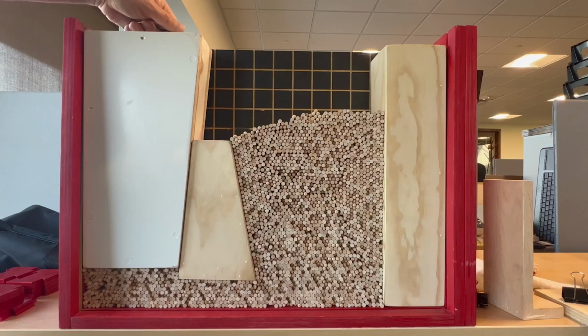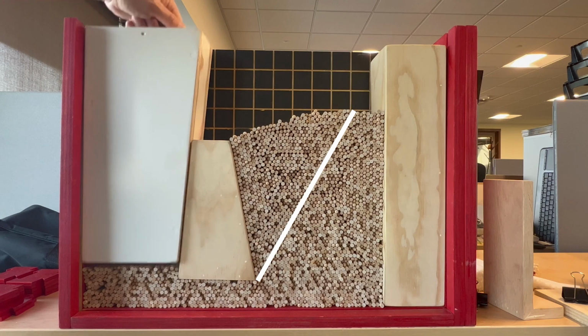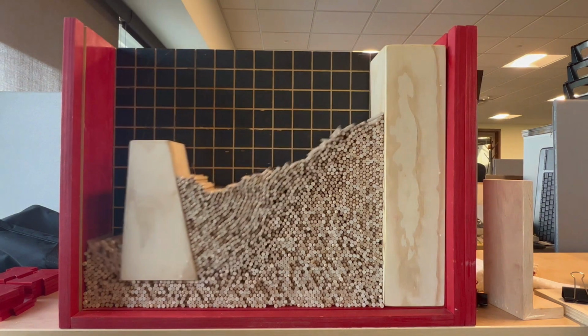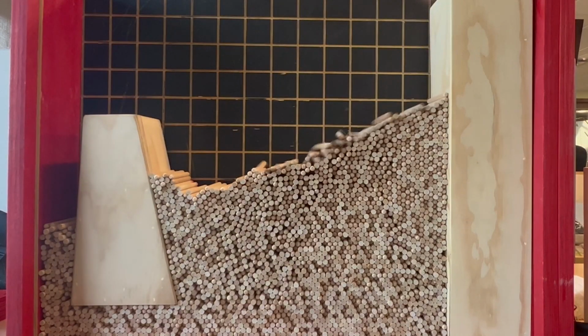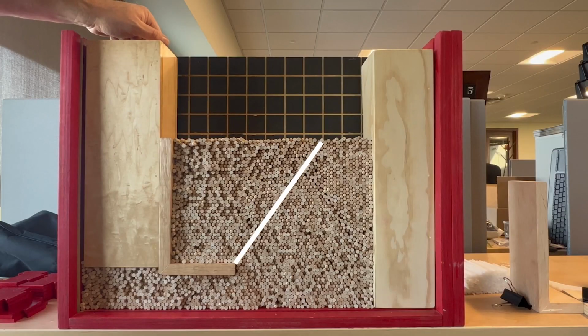Well, we can put it to the test with wall in a box. Here, you can see a simple gravity wall we built to fail on purpose. When we move the supports out of the way, you'll see what happens. As things start to move, you can notice the failure wedge that forms in the retained soil, just like our theory predicts. You might also notice the soil moving down the back of the wall, causing the friction, which we had also assumed. Here, you can see a simple cantilever wall.